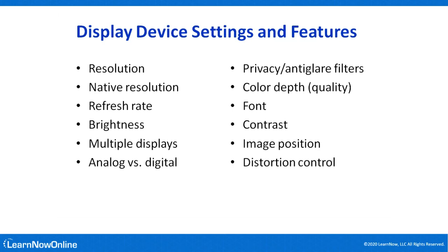Distortion can appear as curves, waves, or patterns in the video image, typically caused by electromagnetic interference. So sometimes you can just fix the problem by moving whatever is emitting the EMI further away from the monitor.